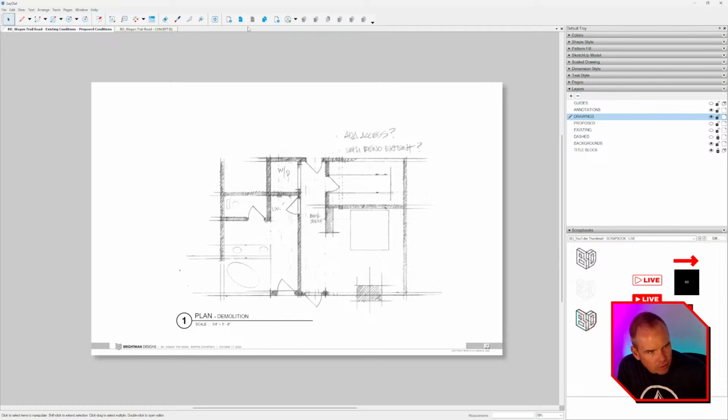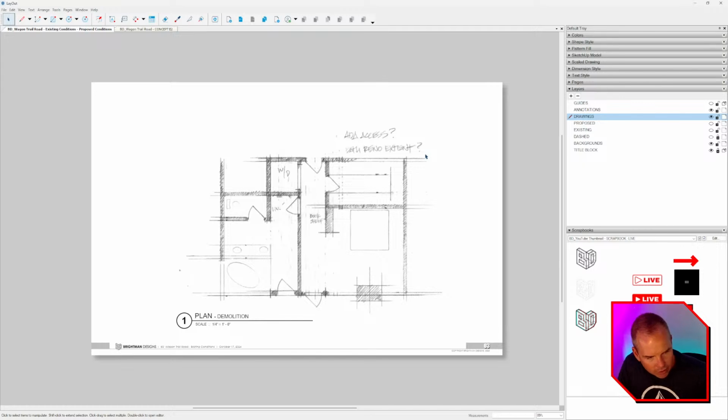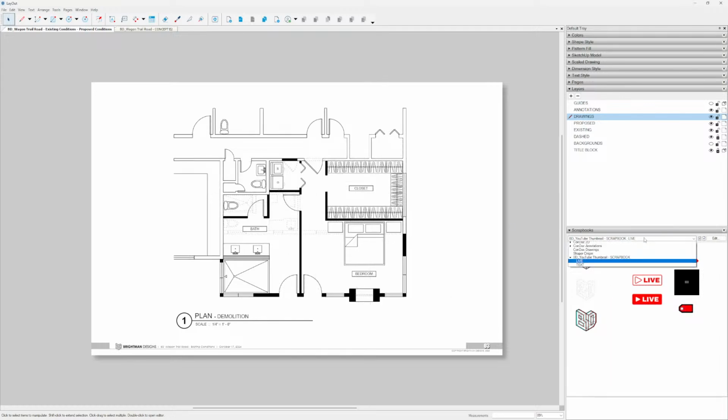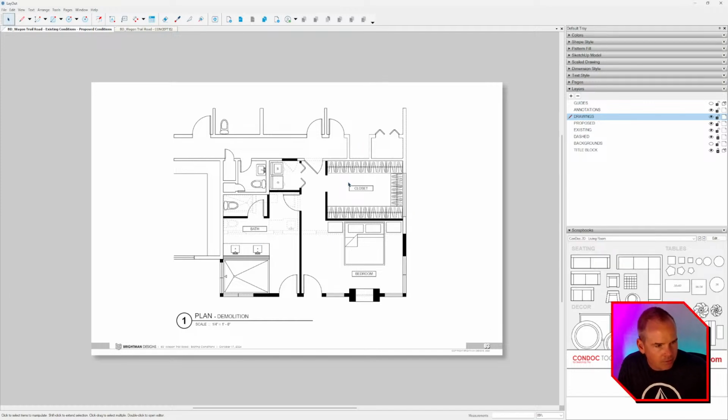So we used our existing conditions, printed it out, made some sketches with trace paper, and then imported that, scaled it, and tightened it up with layout in our ConDoc 2D scrapbooks, creating these scale drawings in layout. The reason we did that is because it's so much faster to make decisions on the fly, to sort out the plan, infinitely faster than drawing this in 3D and having to model everything in 3D to net a clean plan like this.